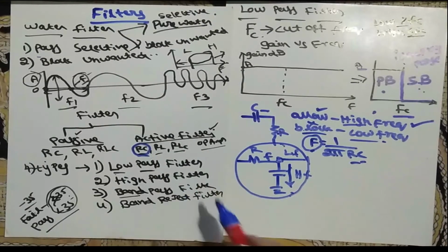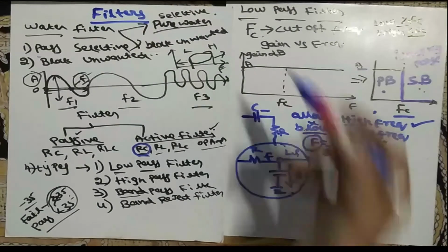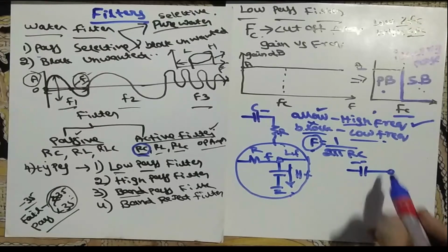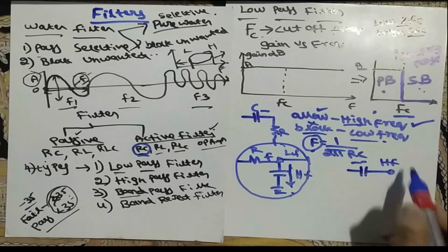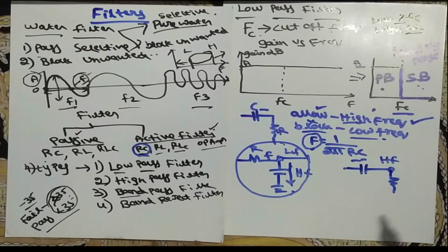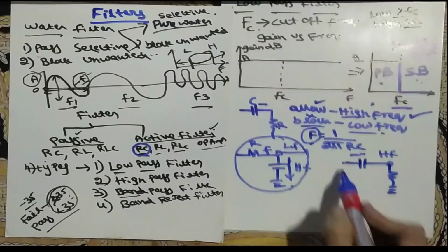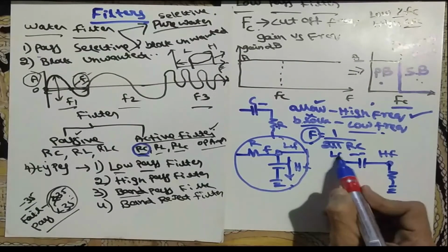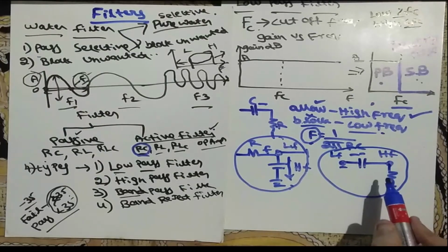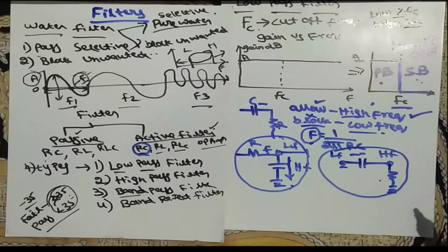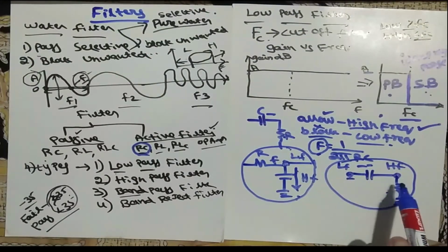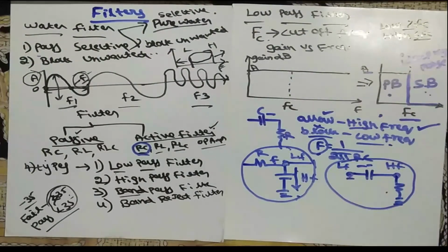This is the structure of any low pass filter, if you are taking the example of an RC circuit. So what happens in the high pass filter? In a high pass filter, first we allow the high frequency through the capacitor, and the resistor is grounded just for charging and discharging purposes. The low frequency will be blocked right here, and this type of RC circuit we use for the high pass filter. So this is how the RC circuit can be drawn for low pass and high pass.